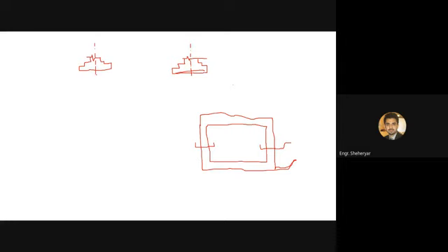Okay, one point I forgot to tell you: this long wall short wall method is only applicable on symmetrical footings. Yes, it is applicable on symmetrical cross sections. For example, this is a symmetrical cross section. Both sides of the foundation are the same across the center line of this foundation or cross section. So if the foundation or wall cross section is not symmetrical, you cannot apply the long wall and short wall method on that structure.